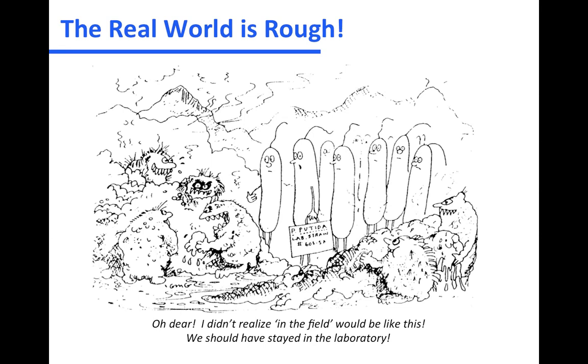Therefore, passages in the laboratory generating a bioaugmentation inoculum doesn't change Dehalococcoides. You can bring it back to the natural environment and it's competitive, because it's so specialized, it can't do anything else. And that's probably a reason why reductive dechlorination can be stimulated by bioaugmentation, but these other processes like metabolic oxidation are less likely to be successfully stimulated by bioaugmentation.